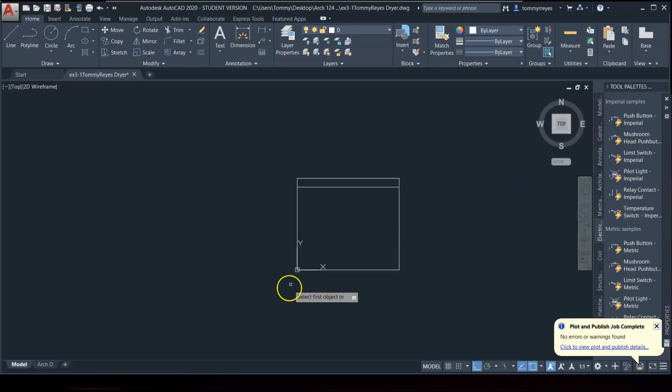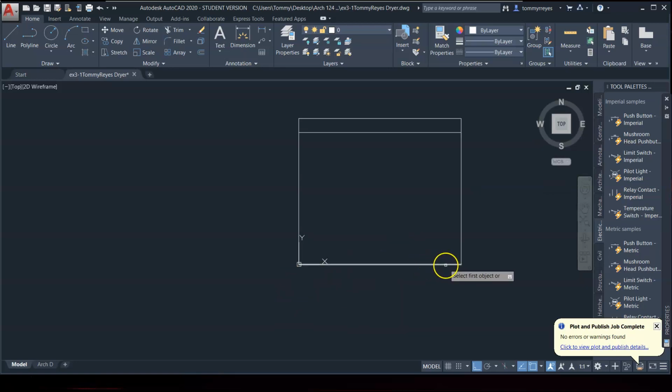Enter. Now we get to select our object, and we can select two. We have to select a first line and a second line. What this fillet does is it allows these two lines to form a curved line together. And watch what I mean by this.